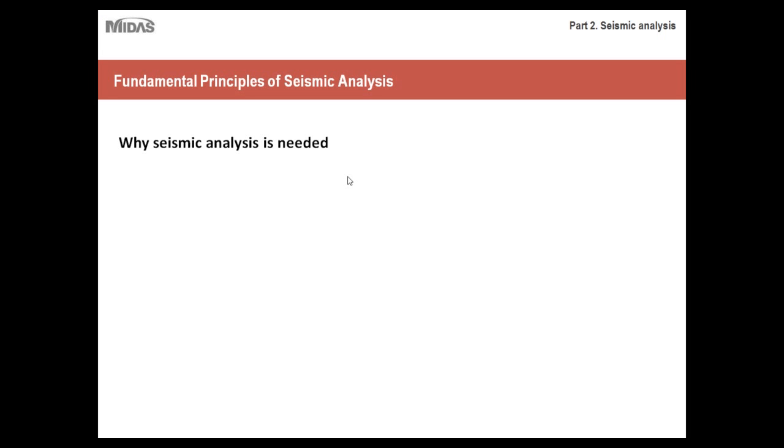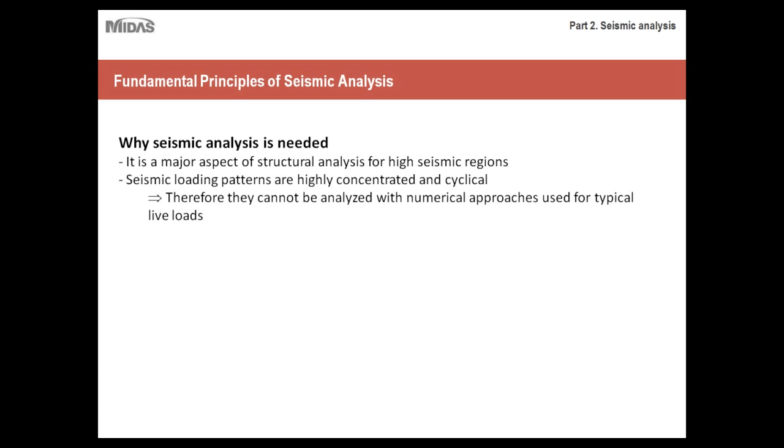First, why is seismic analysis needed? First and foremost, it's a major aspect of structural analysis for high seismic regions, such as California, Hawaii, Alaska, etc. Seismic loading patterns are highly concentrated and cyclical, which means they vary depending on time. Therefore, they cannot be analyzed with numerical approaches used for typical live loads.